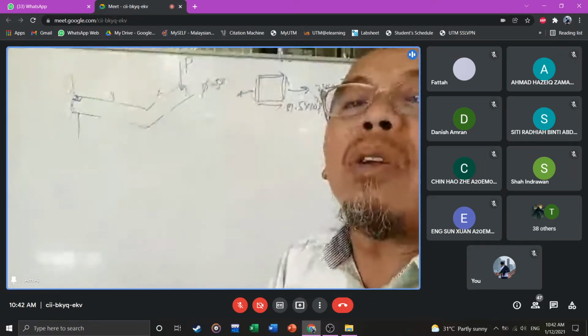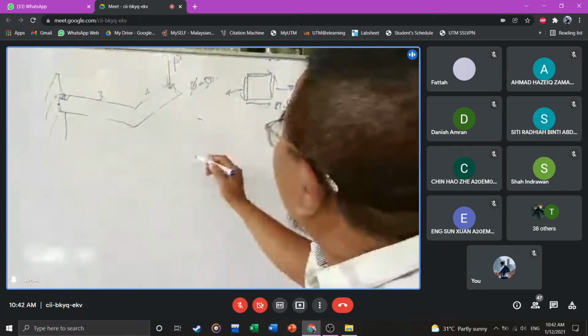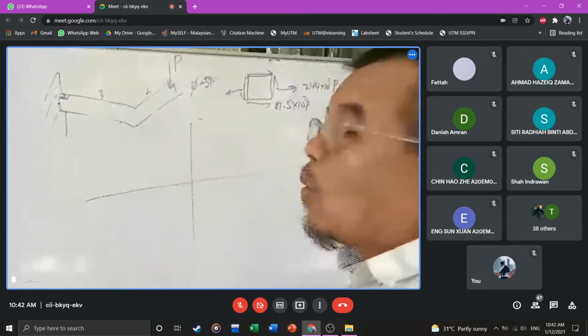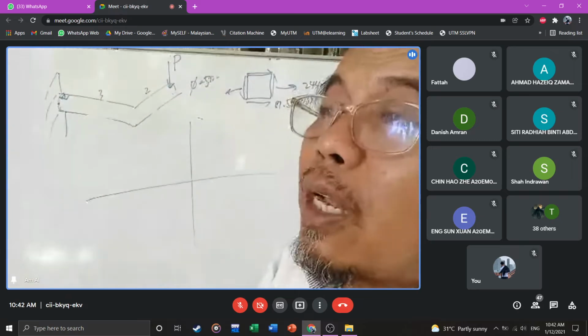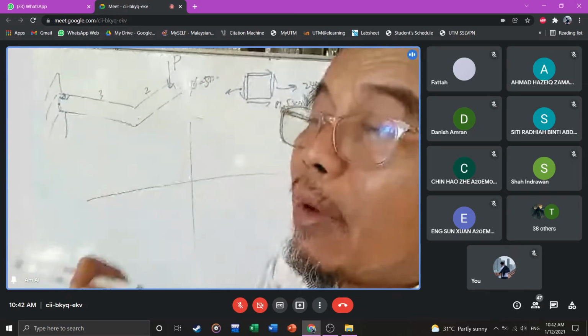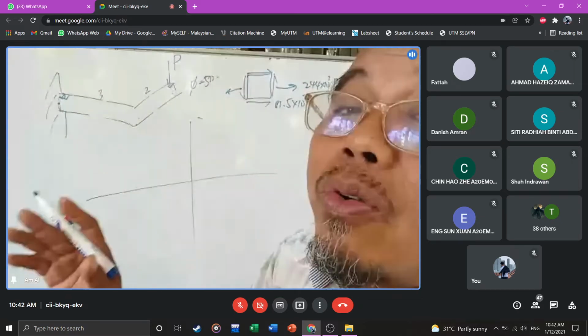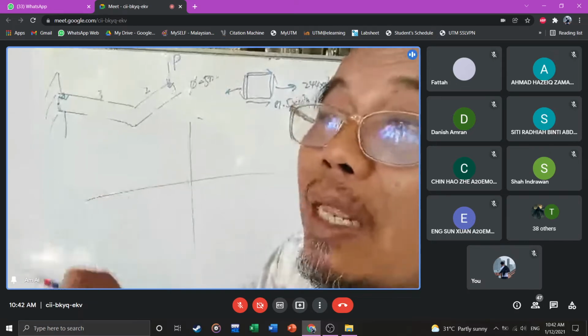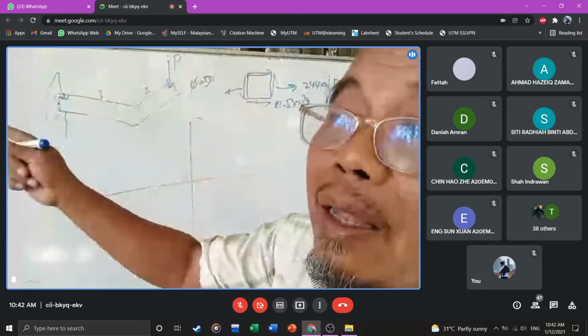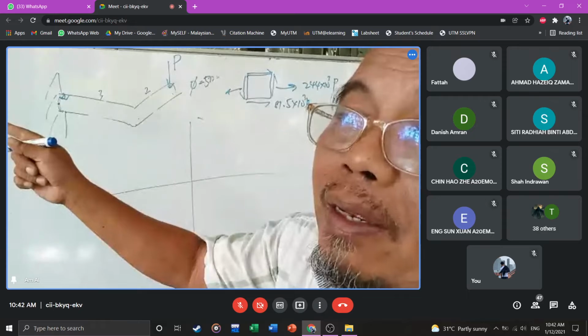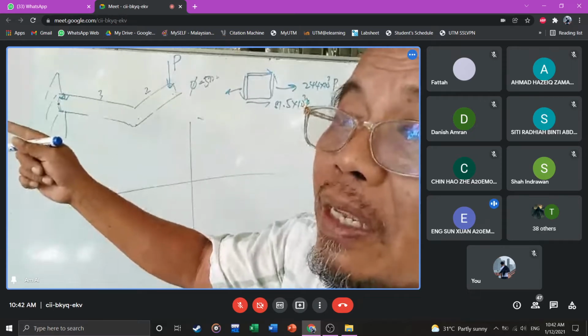Do the question and do a quick Mohr circle. Why do I want to find the Mohr circle? I want to find sigma 1, sigma 2, and then I want to do a 3D Mohr circle. I want to find sigma 1, sigma 2, sigma 3. I want to put into Tresca. Are you with me? Yes.